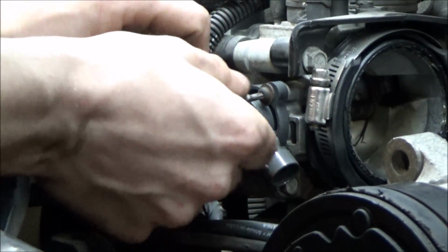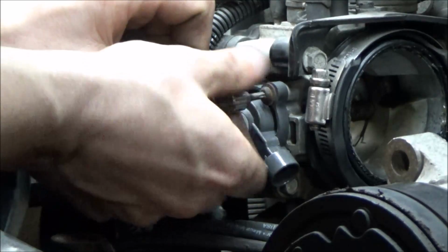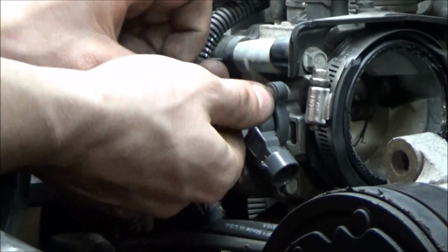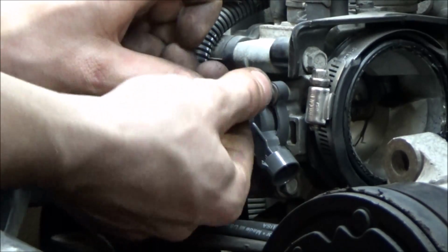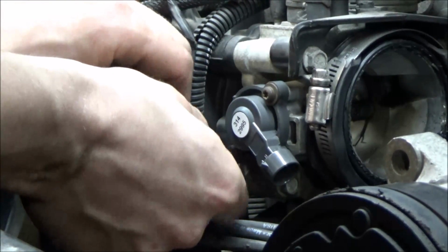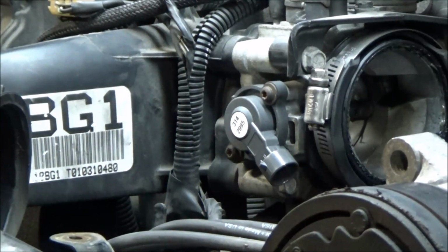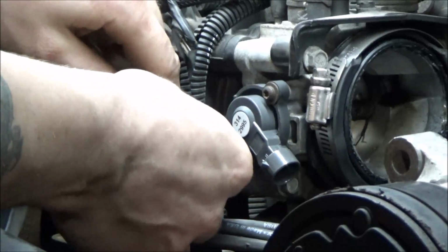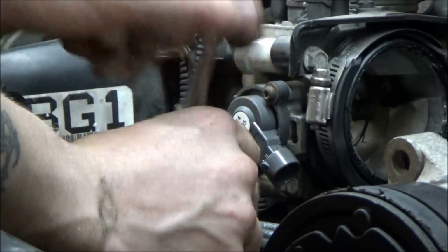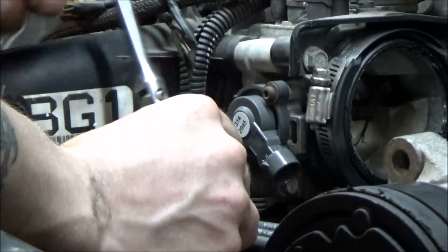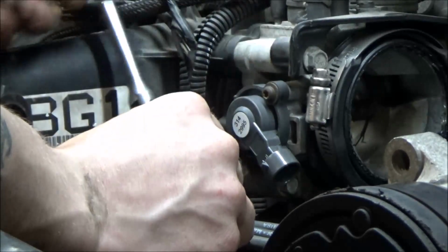You've got to remember, this is a really thin, flimsy plastic housing. These screws do not need to be super tight. You are literally pretty much just snugging this down. That's really all there is to it. Do not go hulking these on here. You will damage your new sensor, almost guaranteed. You also run the risk of potentially shearing off one of these tiny little screws in the throttle body, and then you're definitely up the creek without a paddle.